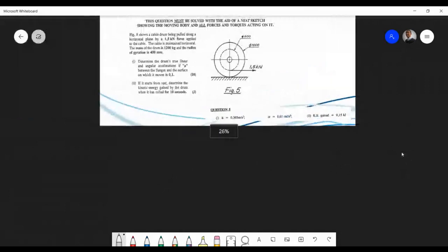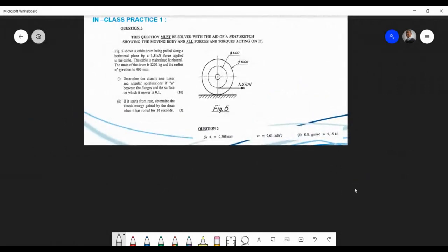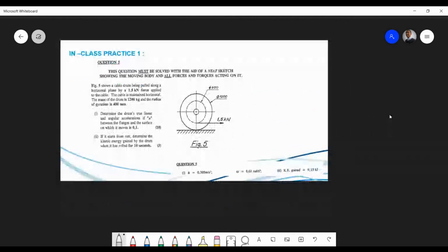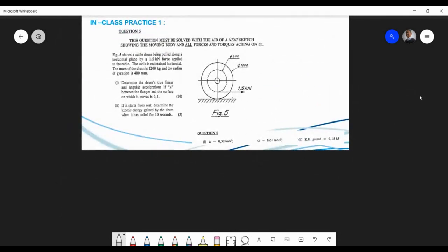Okay, just want to zoom out here. So again, we do exactly the same as before. In this case, if you're looking at the force on the body, it is being pulled this way. So therefore, we experience an angular acceleration going that way, alpha. Our inertial torque will always be there. And of course, we have F mu also going that way. That's the forces on the body.